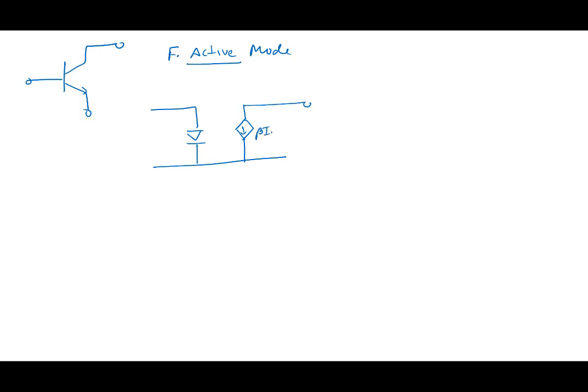Beta IB here, depending on how accurate you want, emitter and base here, forward active. Note that this is IB and this is IC. In forward active, IC is equal to beta times IB. This relationship holds, and the other one is base-emitter voltage is roughly 0.7, right? So we use these things to calculate. VBE is equal to 0.7 volt.